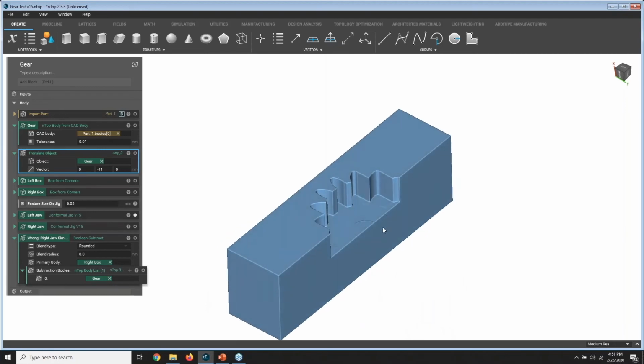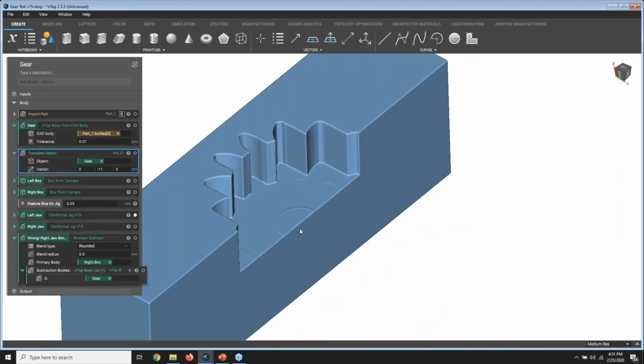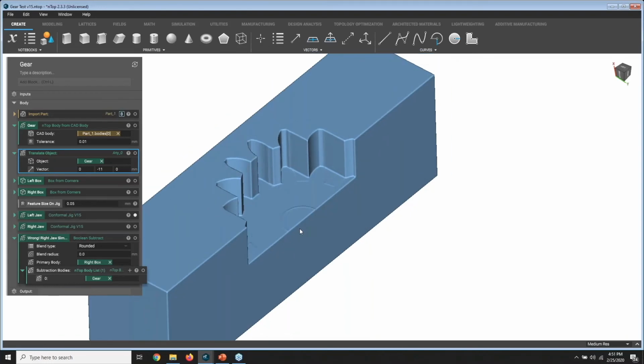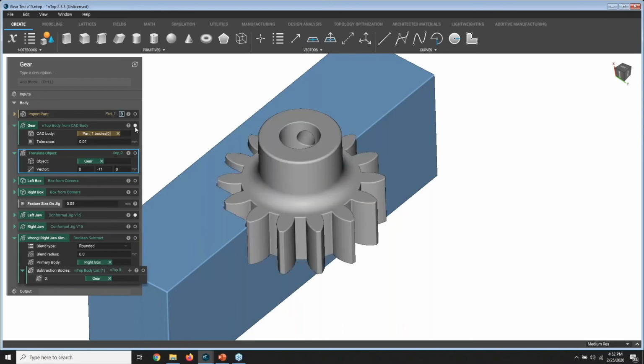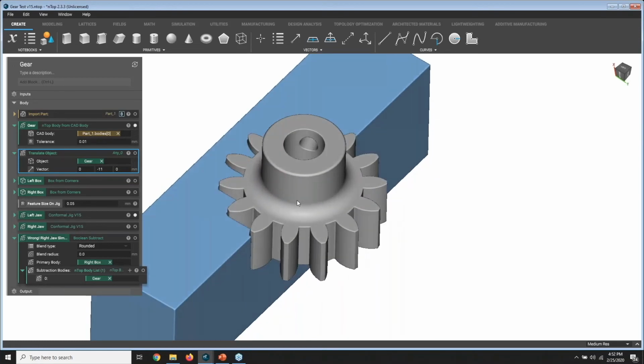Now, one thing that's quite interesting about creating the soft jaw is based on the removability criteria, we actually could end up with a design that can be subtractively machined in addition to being additively manufactured. So really you have the full flexibility here of how you want to manufacture this. As Jack said, depending on what your availability is for machines, you have that flexibility to manufacture this part multiple different ways in order to finally finish the main component that you're most interested in. And so all of this, again, is captured through a replayable workflow that works regardless of what input geometry I put into it, whether it's this gear or whether it's other pieces of geometry like a femoral stem.